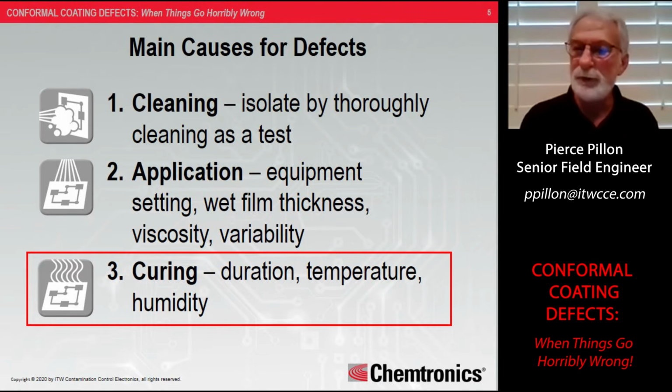And then of course you have the curing process, the time, temperature, in some cases the humidity conditions in which you're curing that coating. If you're not doing it properly, if you're not following the coating manufacturer's recommended guidelines, that could set you up for a coating failure or a defect.